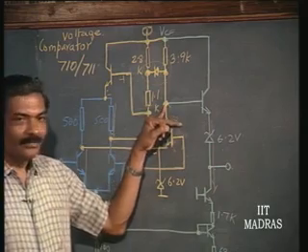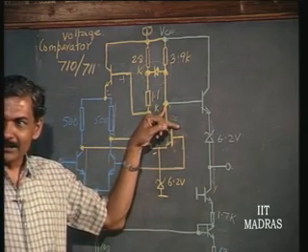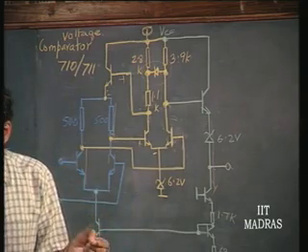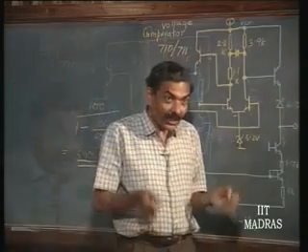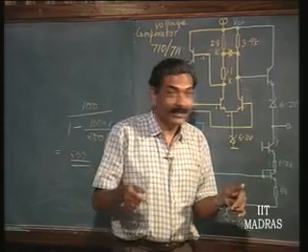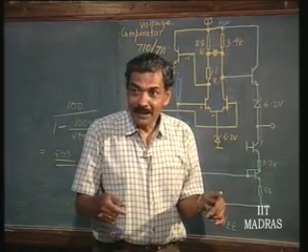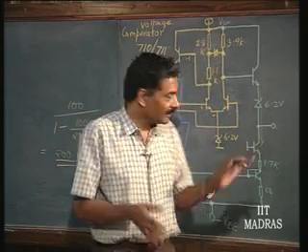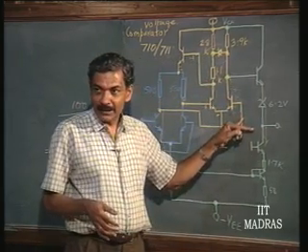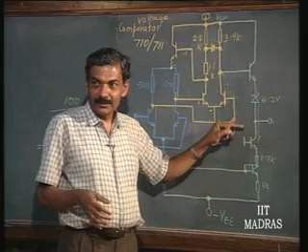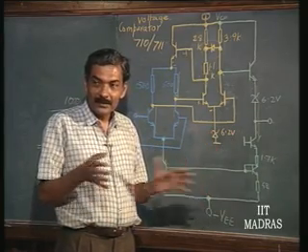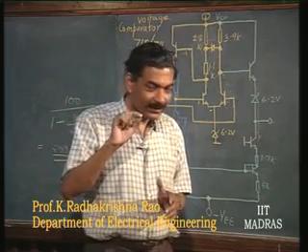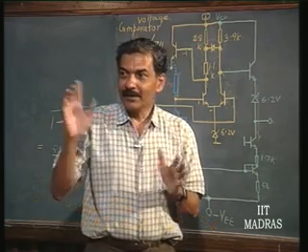But when it is under open loop, if it oscillates, the amount of capacitor that you have to put here may be extremely small, or it is not oscillating because this capacitor is already coming as dominant pole, because that is the Miller effect capacitor. So, do not assume that there is no dominant pole here. That may be quite dominant enough, under this open loop situation, even if there is small amount of negative feedback, not to cause any oscillation.